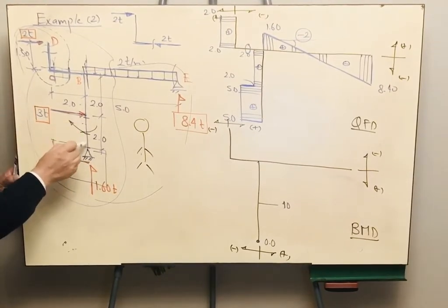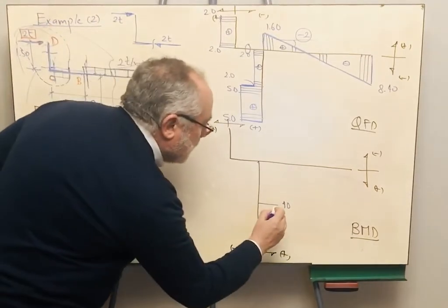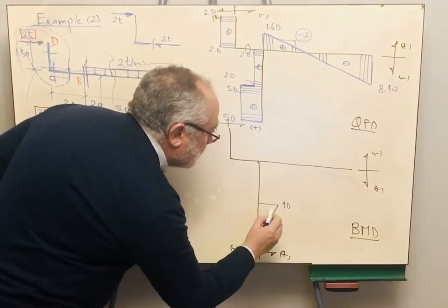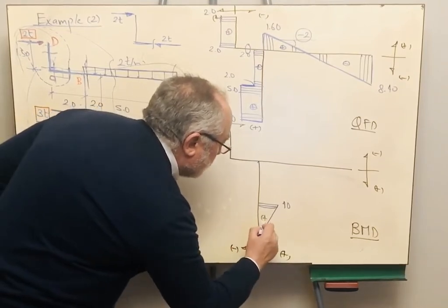I don't have any loads, the shear is constant. Therefore the moment must be linear. Okay, and this is positive.